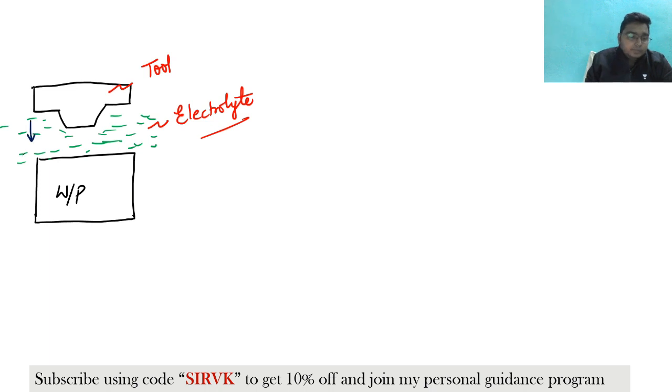Now try to understand here that this tool will move down. Let me connect this tool to the negative terminal, and let this workpiece be connected with the positive terminal of the power source. Since this is connected with the negative terminal, electrons will be bombarding. Suppose the electrons are here, they will get bombarded onto the workpiece, and whenever that happens, material is going to be removed from this workpiece. Let me draw another figure to show what is happening after that.